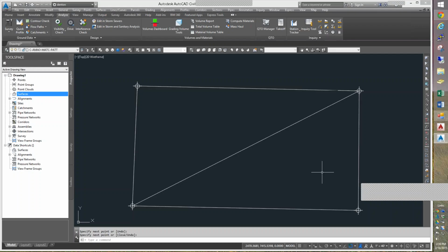The triangles represent lines of interpolation between the points so that the elevation from the first point to the second point is known, and the elevation change to the next point, forming a flat surface or triangle. This field is covered by two triangles. A line of interpolation is going up through the middle.